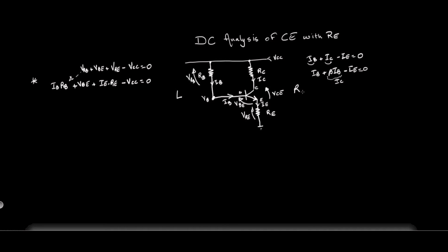And let's work on the right-hand side of the circuit and also establish Kirchhoff rules. And we now know that we also have a voltage VC here, right, against VR, or you can call it VRC if you want. Let's call it VRC, okay? So let's go ahead and do that. So we have VRC plus VCE plus VRE minus VCC equals 0. There you go.